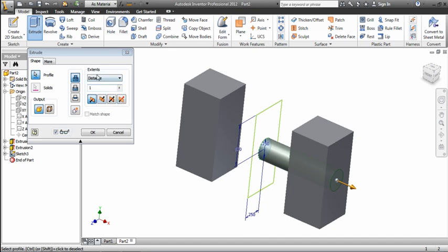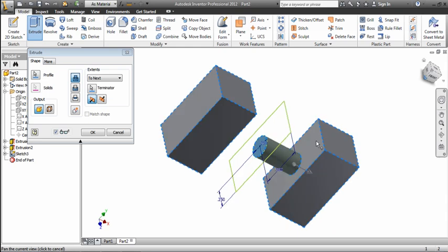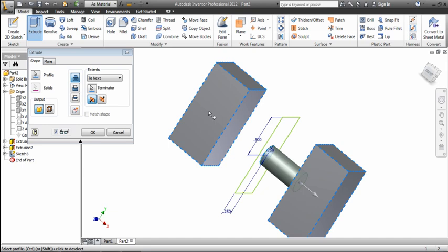I've already shown you all these, but I can change the distance to say 2 next. What this is going to do is it's going to extrude this until it runs into the next object. So if you want your extrusion to go until it touches the next object, then you can do that by choosing 2 next. Now if I wanted to touch this object, all I have to do is do direction 2, and now it's going to go until it touches the other object. So you don't have to guess how far away this is. We know how far away it is because it's a simple measurement that we did. It's 0.5 away. But we might not have remembered that because we may have a lot of different extrusions or features that we've done, and we don't want to have to go through and measure how far away this is.